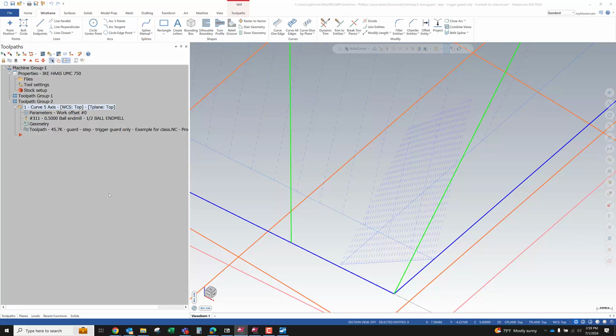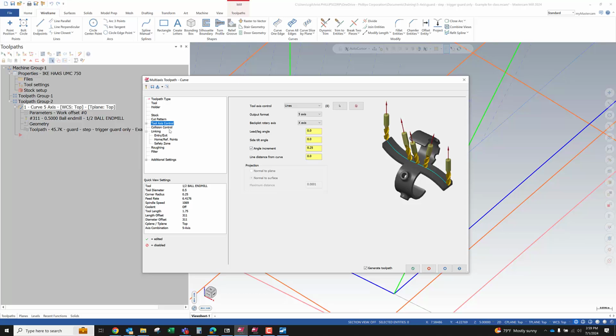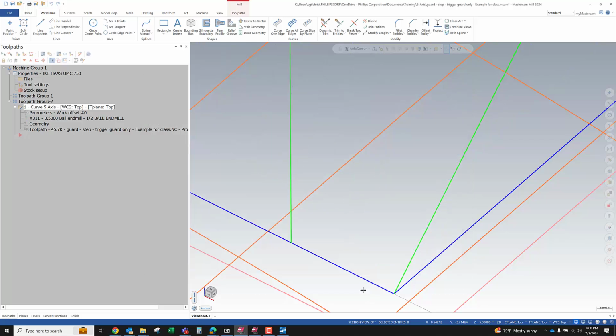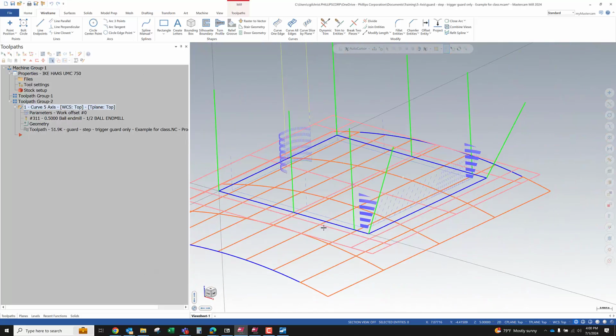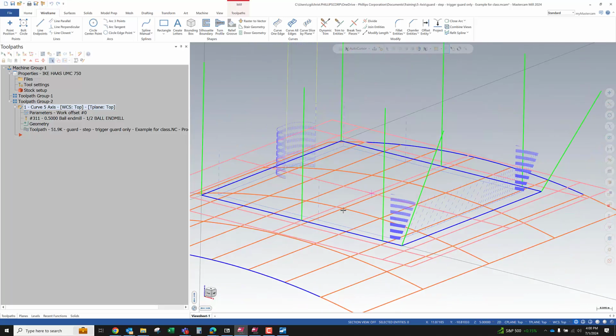10 is too big. So you don't want a maximum step size under the cut pattern here that is longer than the actual geometry you're driving. I'm going to go back to 3. 3 was good. I could try 5. I could try sneaking up on it. And I can always add filtering if I really am like, hey, I don't want this extra vector here, man.